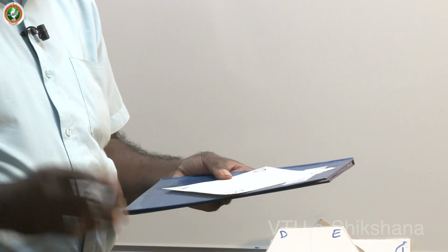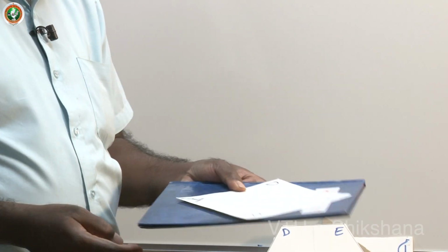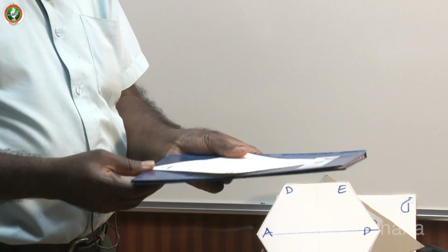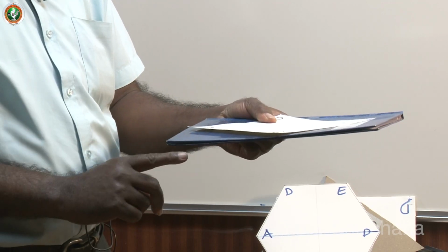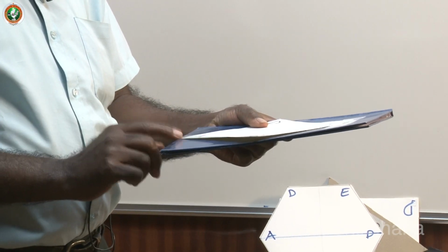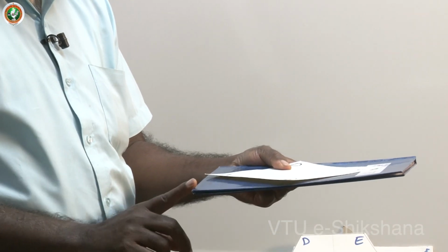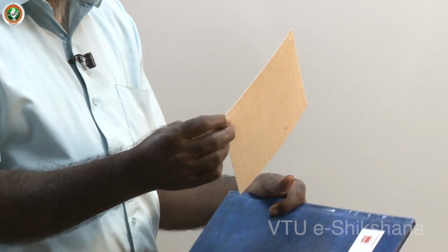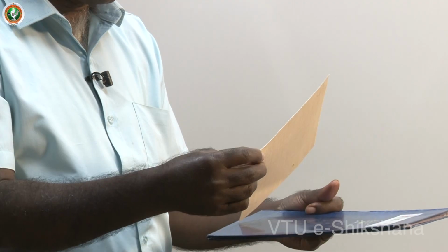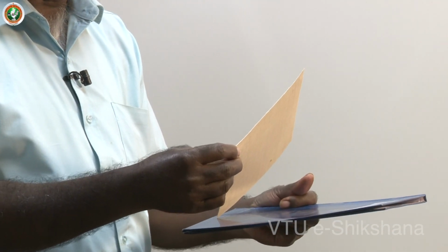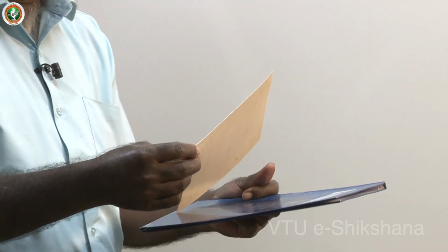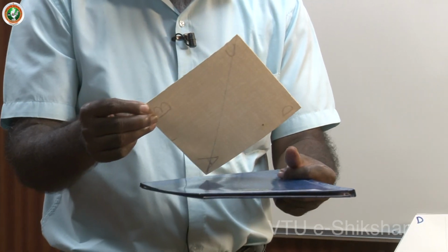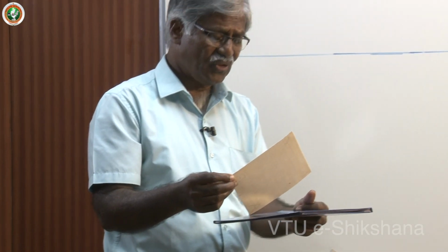Now I will have a simple position of the lamina. The square lamina has a corner on HP. You have to keep it like this only. So for example, this line is perpendicular to VP, say. You have to keep the corner on that line which is perpendicular to VP, so that if you tilt it, give inclination only to HP, these two sides are going to make equal inclination with HP. Sometimes they add that condition also. You don't worry about that. Automatically you will get that condition. See, in this case, these two sides are making equal inclination with HP. So automatically you will get it.